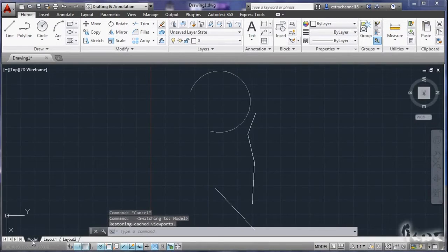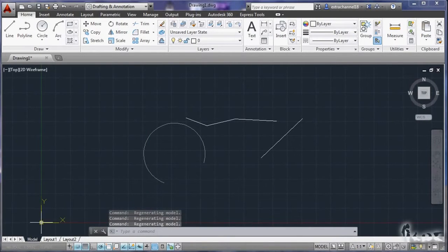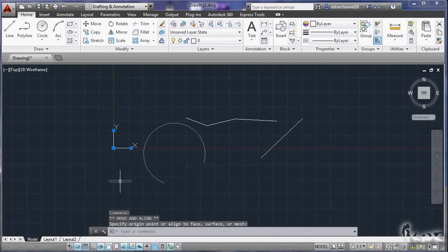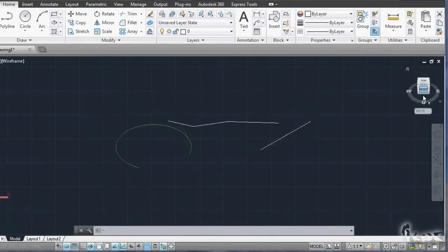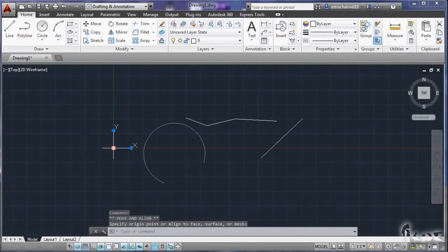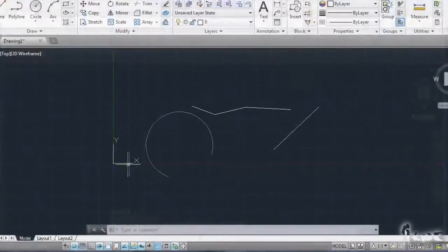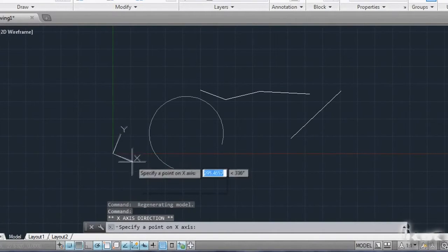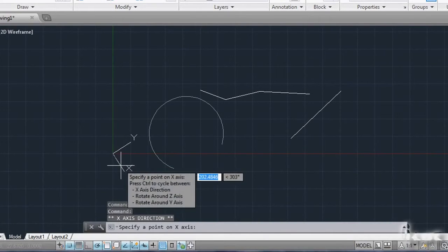If you need to rotate the Cartesian axes, they are like objects in your workspace that you can pick and move. This will locate the X and the Y axis, and so the direction and the positions. There is also the Z axis, but this is for 3D models that I will show in another tutorial. The blue square will move the system, whereas the rounded ones will rotate the graph, but not the drawings inside.